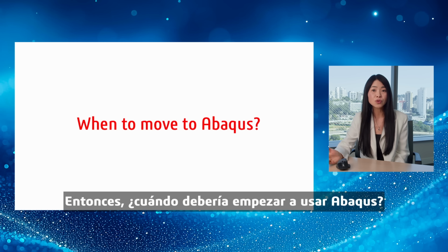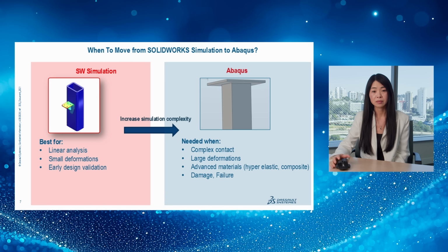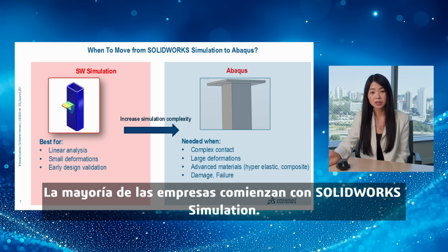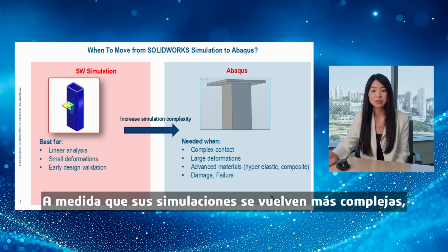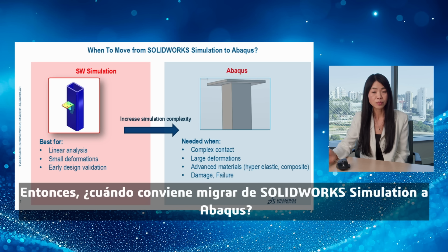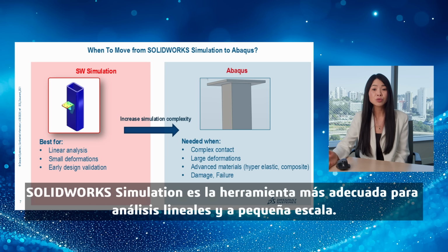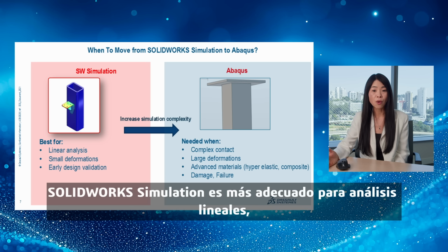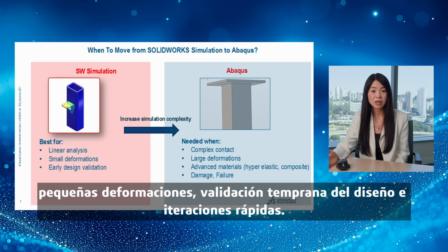So when to move to Abaqus? Most companies start with SolidWorks simulation. As their simulations become more complex, more nonlinear, they eventually need Abaqus. So when to move from SolidWorks simulation to Abaqus? SolidWorks simulation is best for linear analysis, small deformation, early design validation, and fast iterations.